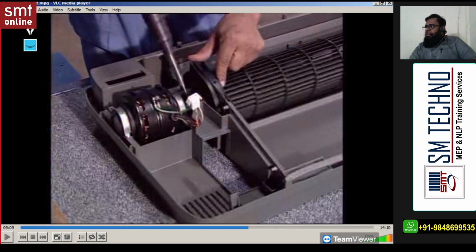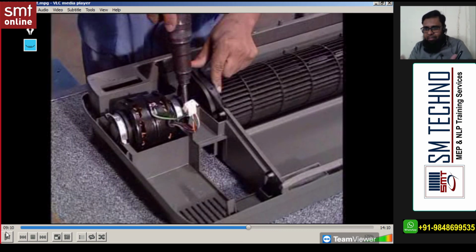So this is also one major difference between FCU and AHU. We will discuss AHU later, but at that time remember this point. FCUs are direct driven, AHUs are belt driven. At present, FCUs. See, I'm mixing some points, so don't get confused. In the next classes, we'll discuss AHU and compare it with the FCU, etc.